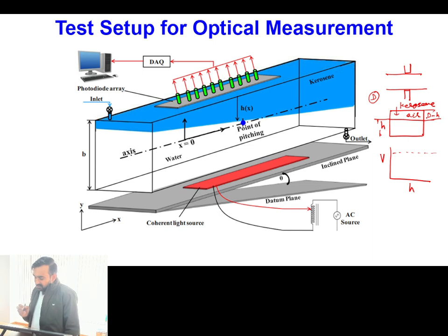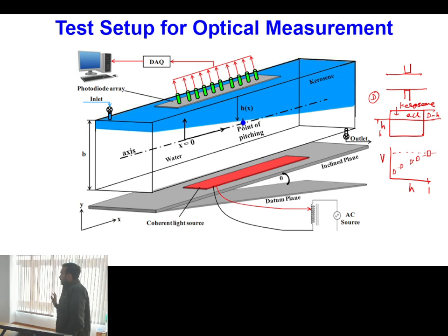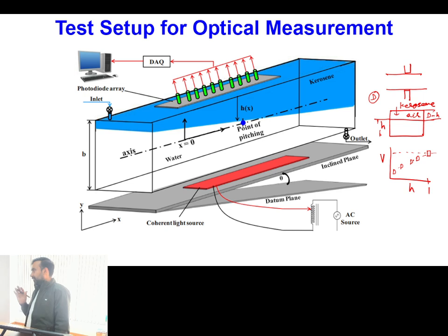Okay, so in this scenario we observed that when H was large, or close to unity, we had pure water and a high value of the voltage signal. But once we started decreasing H, it means we started increasing the amount of kerosene in the tank. Corresponding to that, our voltage signal decreased significantly. Is this point clear? So this we have actually seen in the previous lecture.